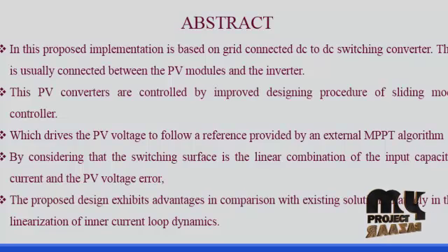The proposed power and frequency characteristics of the hybrid unit and of the microgrid operating conditions are such that the hybrid unit may supply the maximum PV power, match the load and/or charge the battery, while maintaining the power balance in the microgrid and respecting the battery state of charge limits. These features are achieved without relying on a central management system or communication, as most of the existing algorithms do. The control strategy is implemented using a multi-loop controller, which provides smooth and autonomous transition between the operating scenarios, and this proposed implementation is done in the MATLAB simulation environment.